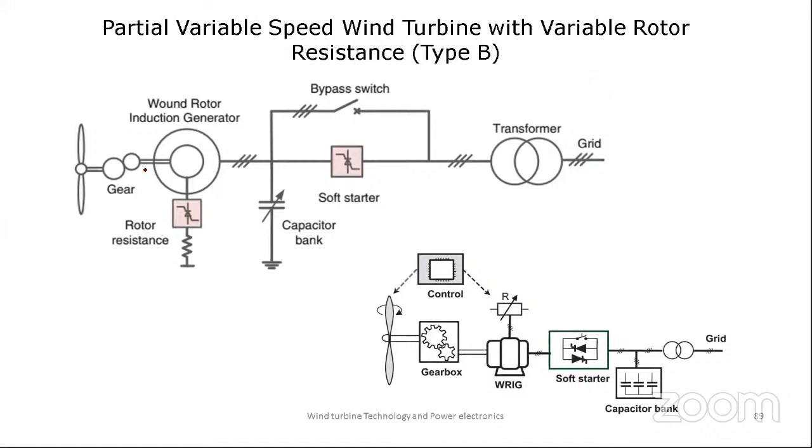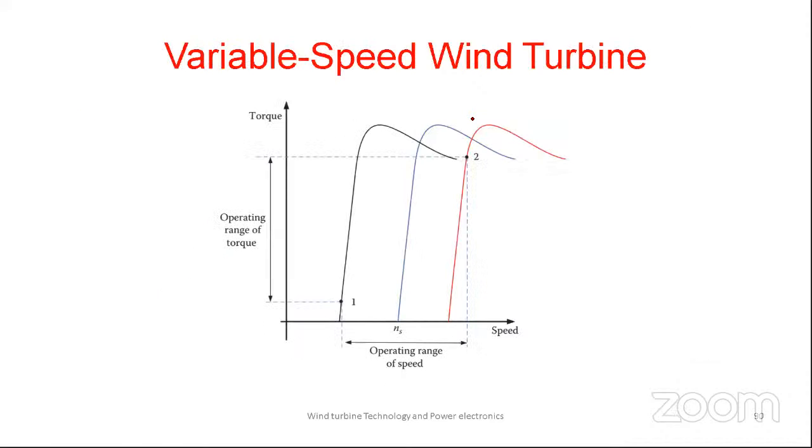So here also, when the power generated is more, I mean, when the wind speed is more, what will happen? Whatever power is generated goes towards the resistance. The resistance generates heat, which dissipates into the atmosphere, right? In such a way I can limit the speed of the rotor. So that is the control of this kind of turbine. The next one is the variable speed turbine.